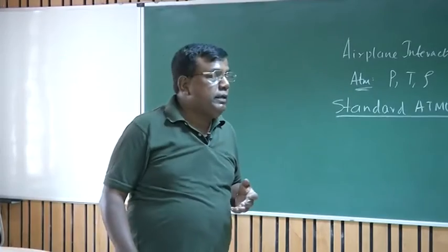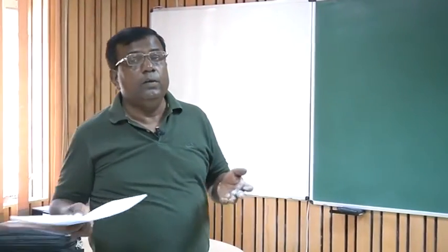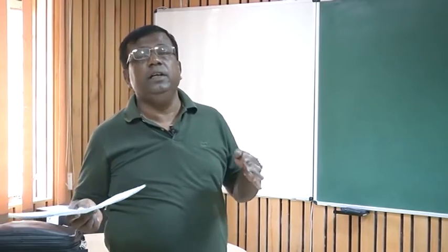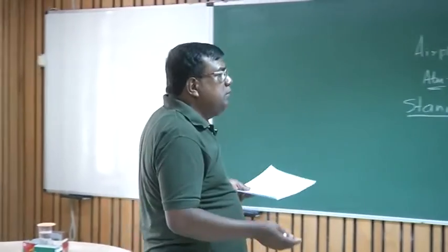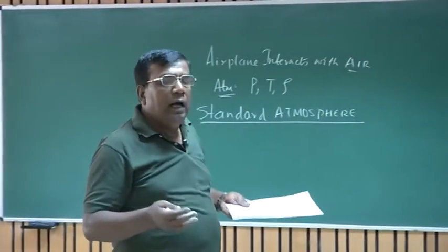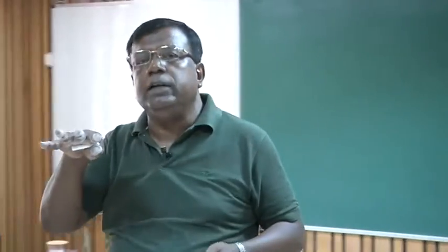So I cannot expect they will experience the same force, for other conditions of speed and area being same. So when I want to compare two airplane performances, I need to compare them on a common platform or common atmospheric conditions.